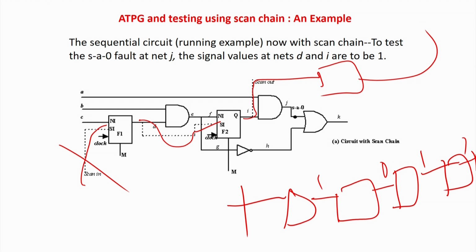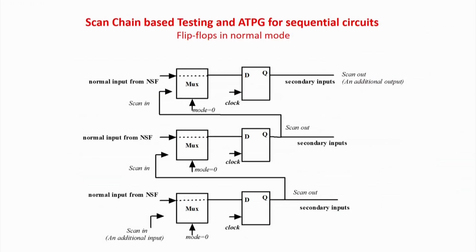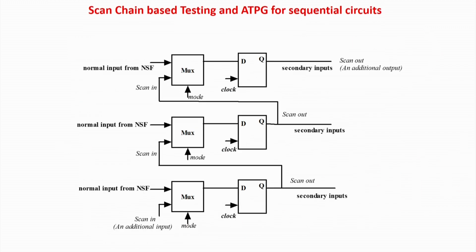So wherever you want to make 1, 0 and 1, you can just make this running sequence and load the shift register using the sequence and a clock. That is pure, very simple second year digital fundamentals. You can easily apply this and set the flip flops, and then again bring it back to the normal mode and to the test. I will give you an example to show you very explicitly, but I have just given you the idea.